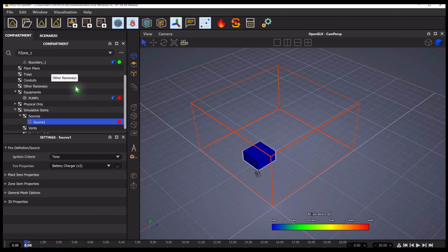Now where is the fire source? The same procedure can be repeated. You click on this wire box, drag it all the way along and put it over here. And notice that it disappeared. All it means is it's hiding behind this box over here. For it to be visible, this is already selected, go to the fire positioning tool here, and you see these positioning handles appear. You can move this around, and there you see the fire appears from here.